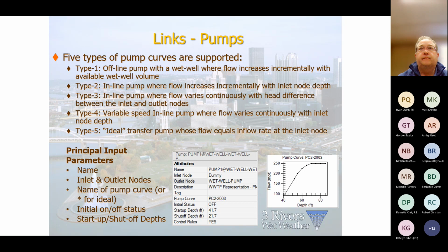Because some of these models originated as conceptual planning models, and we have improved them since, but maybe there are still places for improvement. So make sure that there are actually 2, one in the structure and one at the end of the pipe at the river, but that's unusual. So that's why I'm suggesting, look at the drawing, maybe you can eliminate one. If you don't have the drawings, go look at it in the field and see if you can find it. Now, sometimes, as I said, they're submerged, so it's hard to see the one at the receiving water.